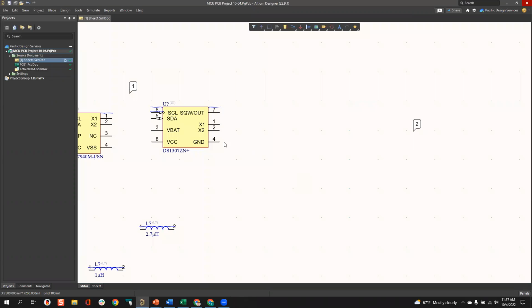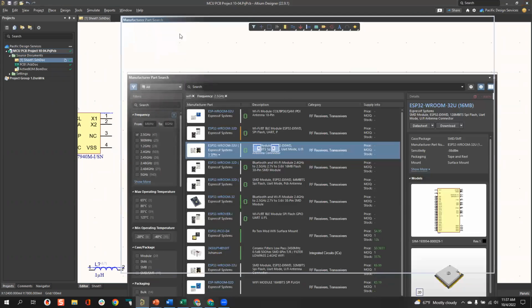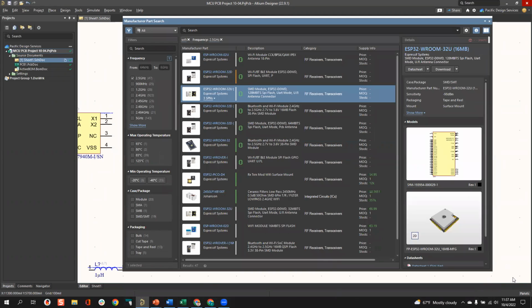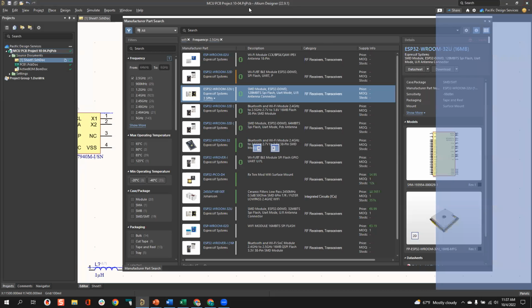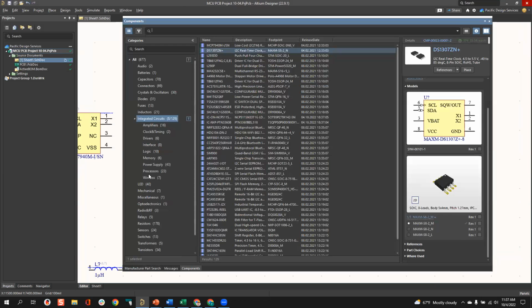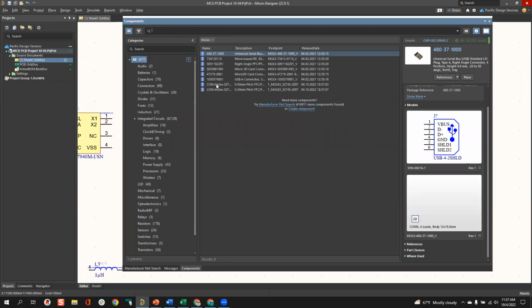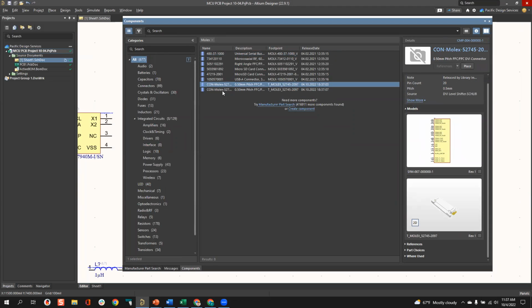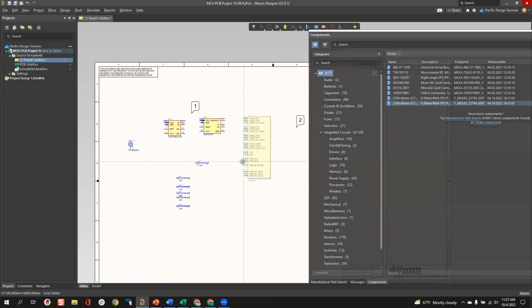We actually now have those components in our library. If we bring our library back in, we can go over to our component library, which is closed, it looks like. But in my component library here, I could drill in, but let's just do a search here on Molex connectors. Look at all my Molex connectors here. And here you see the Molex connectors that were just brought in, the 10.4, it's time-stamped. I can actually go ahead now and drop those into my design, and I'm continuing to work, okay?